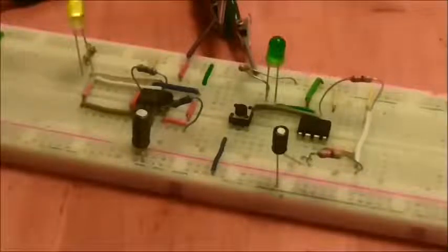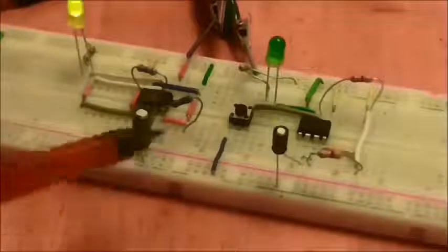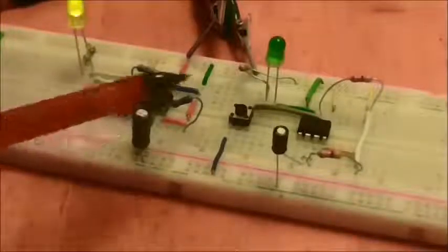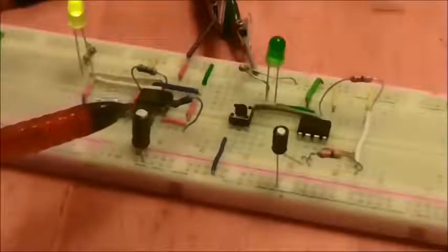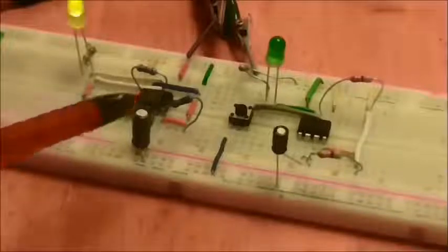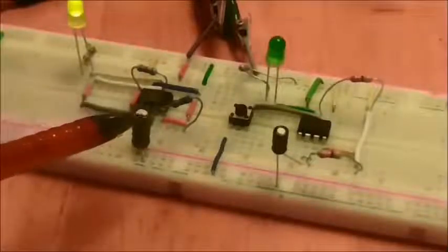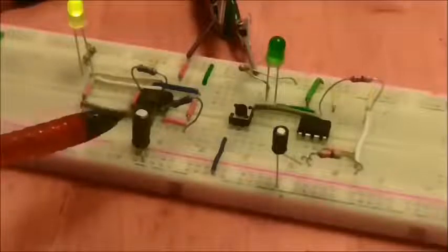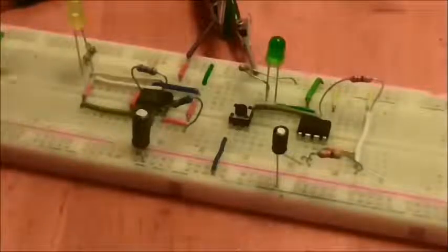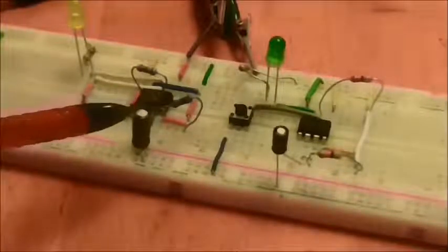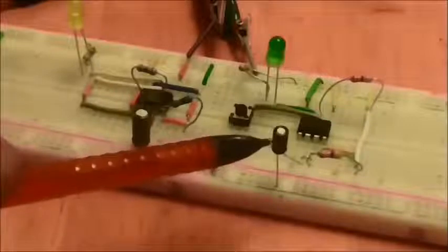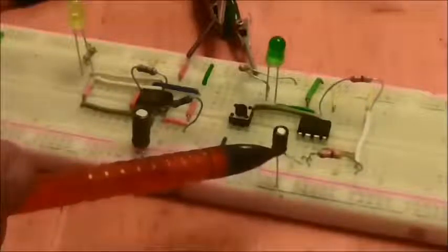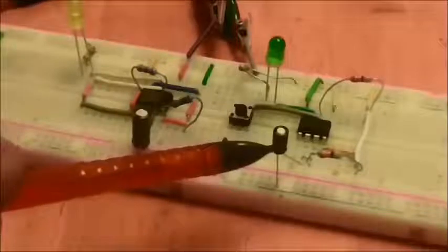Well, it looks as though it's slightly under 1.5 seconds, and the problems here are the quality of the components we're using, I think. These are 1% resistors, but the tolerance on this is marked as K. So it could be as much as 10% under, or as much as 10% over. And that'll give us under 1.5 seconds or over 1.5 seconds. Using a K capacitor is done quite often because they're cheap. This one is a slightly more expensive capacitor. It's marked with a J, and that means it's only 5%.